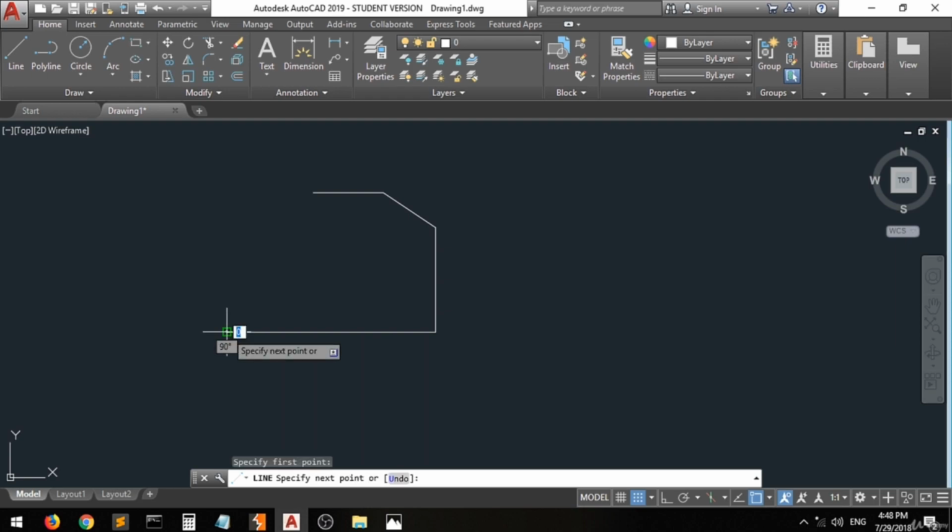Let's start, as we said, from this point. We will move 0.25 in the vertical direction. And again, you can use the coordinate entry, the relative coordinate entry, or the polar entry. Anything you think is easier. So I'll do it in the polar. At 0.25, since it's going in the positive direction, right? Then we'll do it at an angle of 90.